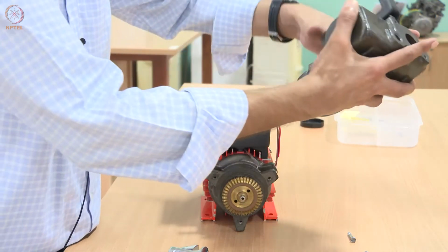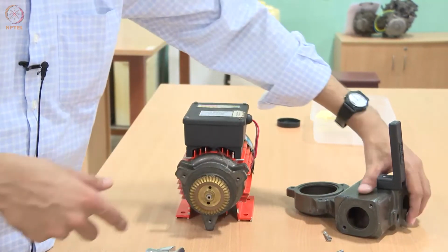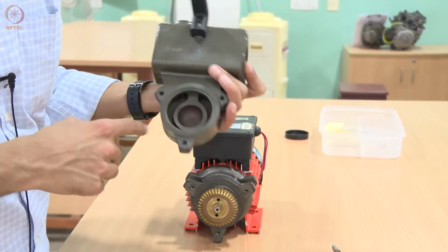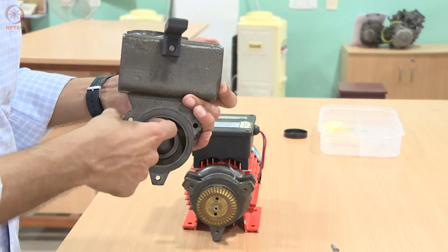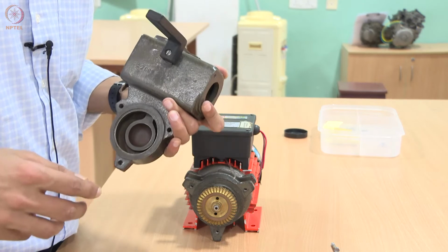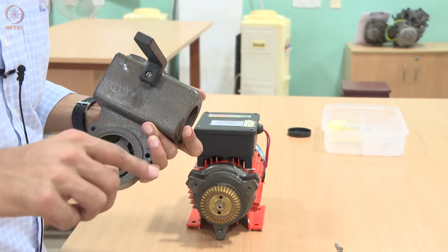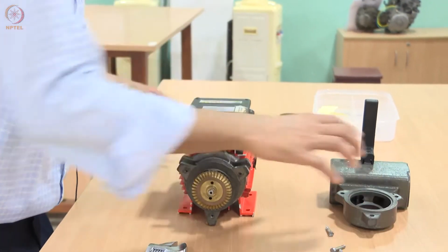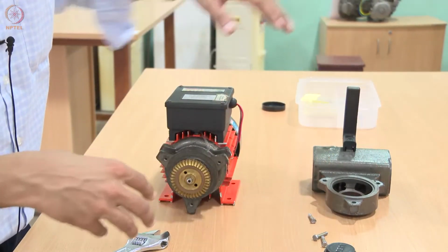and the pump primes itself. So this again, if you look at it, doesn't have what is known as a volute casing. You can see the casing is more or less uniform throughout. In the case of a volute casing, you will have a gradually expanding outlet. Please take a look at the construction of a standard centrifugal pump. It is called a volute casing, V-O-L-U-T-E, volute casing. Again, that is pretty much to do with the impeller and the casing of the pump.